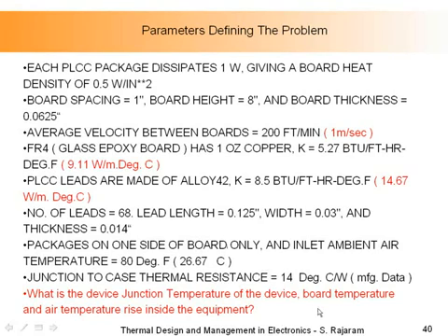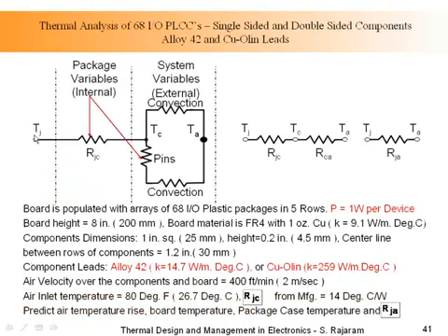So here what we're trying to do is determine the device temperature inside the device, the junction, and the board temperature. You can do the analysis, and typically what happens is here's the package, here's the junction where heat is dissipated. It goes through the case by conduction, goes to the surface. From the surface, it gets carried away by the pins by convection, and on the board by convection.